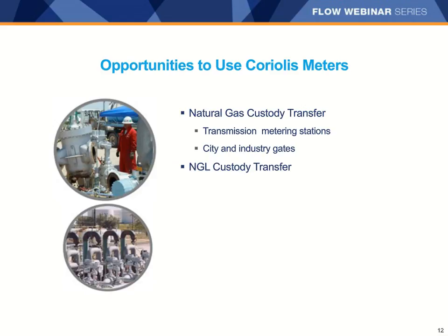This is because the possible range of NGL mixture compositions is so vast that it would be impossible to derive a complete set of volume correction factors that would cover all the possible NGL compositions over a practical range of varying pressures and temperatures. Custody transfer of NGL in mass units is hence becoming an increasingly popular solution to this problem.